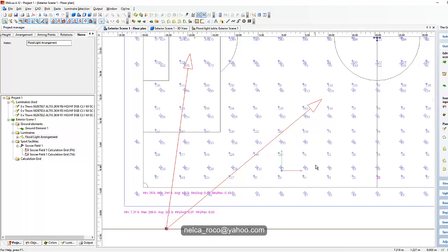So you need to know your fittings, the floodlights, the lamps, because long arc or short arc lamps have different effects also, and the optics of your floodlights, of course. So be very careful of that. But once you get used to it, keep on practicing. It will be very easy for you.